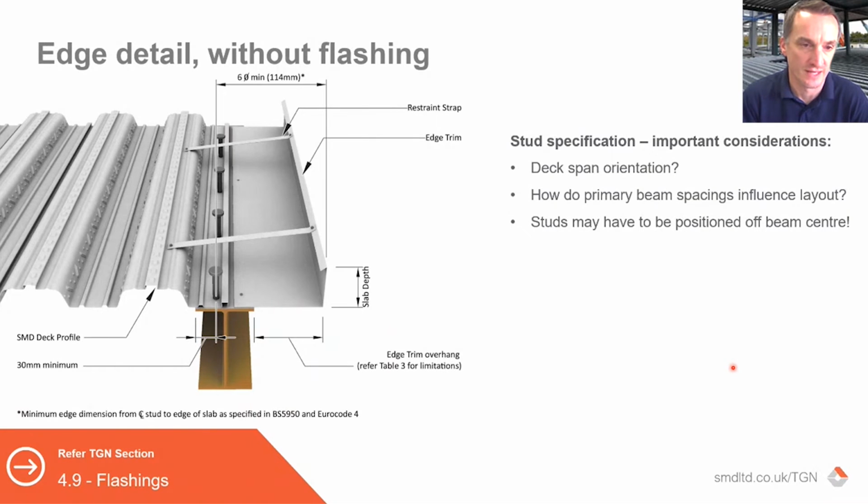There's also then implications of how you get those studs onto the beams with that voided area where the beams are parallel. So this would be a situation where the beam is parallel to the deck span, and the deck has been set out on that beam. So there's no need for a flashing, but you can get the studs onto that beam, welded through the flat at the edge of the profile. That isn't always the case.